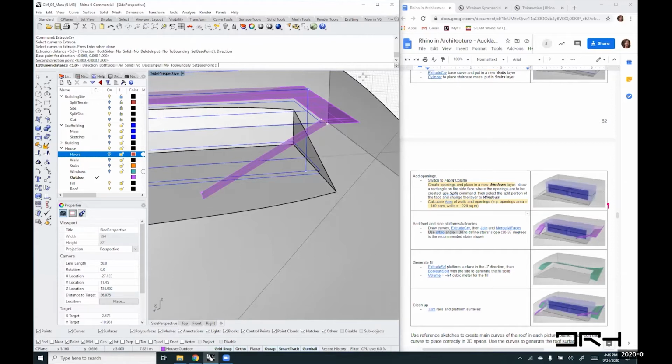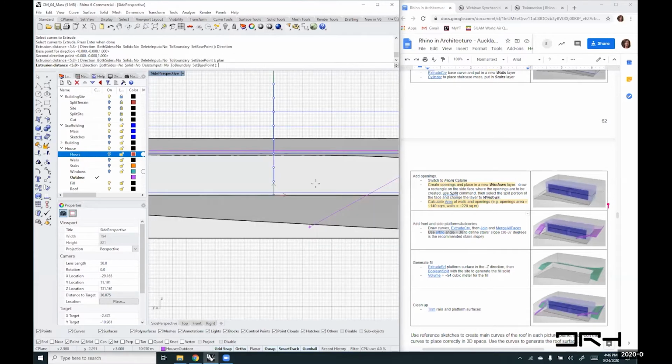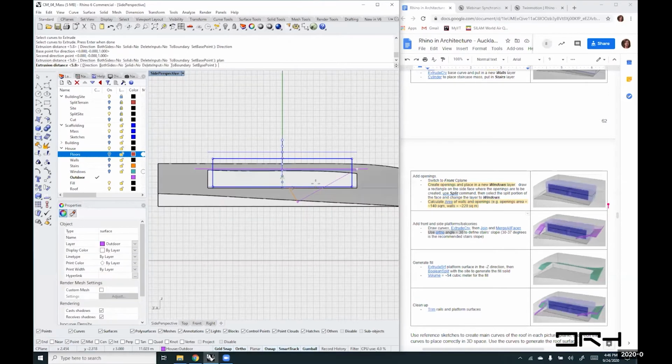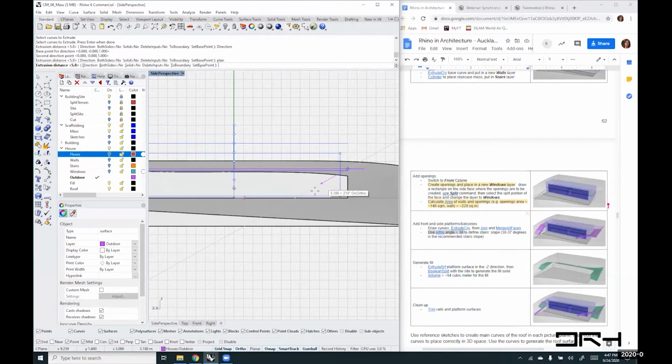So now I feel like I want to go to plan view. And you know that the plan command is actually a command that you can run inside other commands. This is why when I typed plan here, I changed my view to plan, parallel to my C-plane, just so that I have a better visual into where I am going to snap.